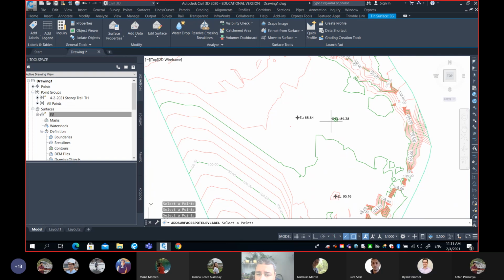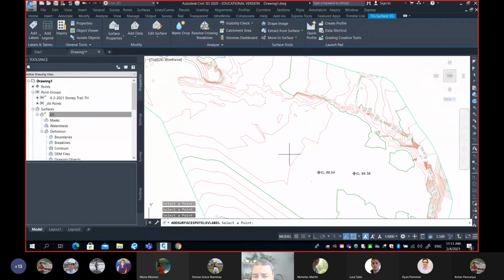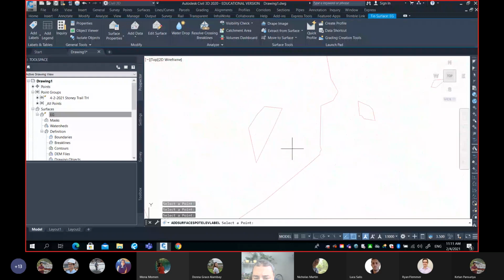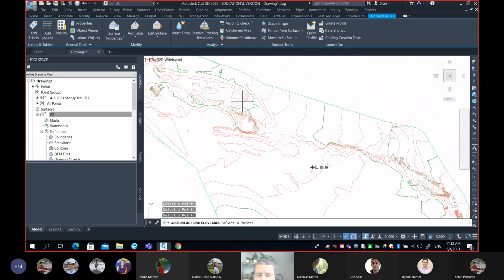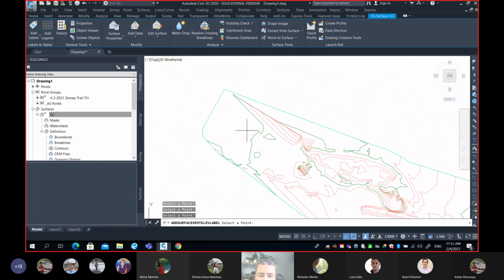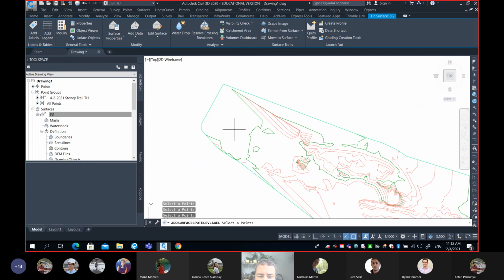No. No. So the spot elevation, please do the following. When I ask you for spot elevation, don't just randomly add them. We add them in very, very few situations. For example, once you see any closed contour line, go ahead and add one spot elevation. Also, I'll show you on the border, for example, here. Okay, so here, you can see this area.